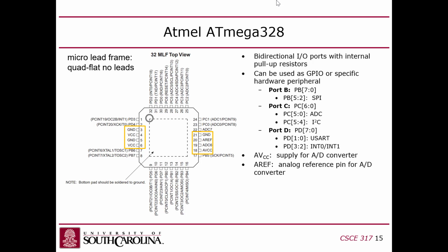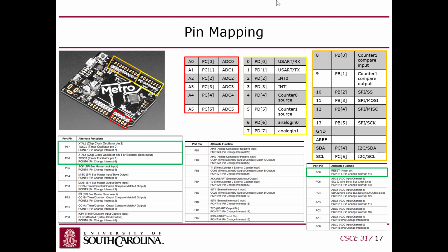But the neat thing is that they are basically GPIO pins. You can set the values of these ports directly from your code fairly easily. But most of these pins, I think most if not all of them, have alternative functions as well, depending on what peripherals you activate on the chip. So for instance, let me go to the next slide, I show it a little better.